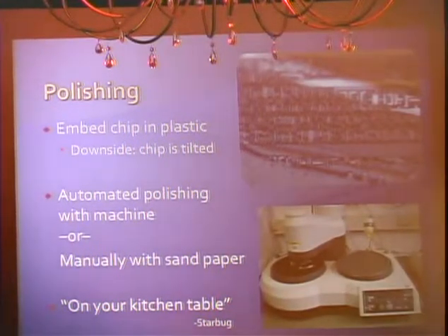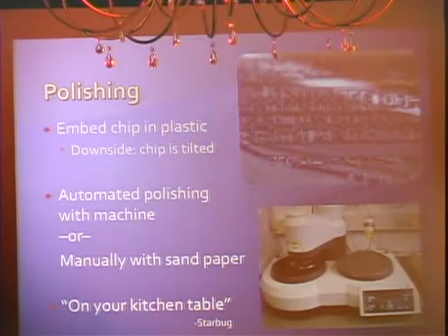One thing you've got to be cautious with, though, is that you don't want the chip to ever be tilted. And by tilting, I mean, imagine this chip to be some 3D structure, like a building. And now if it's tilted, you cut through different floors at the same time, diagonally. Okay? So you don't want that, because you want nice pictures of each layer. And you can imagine how if your chip is only a millimeter square, it's kind of hard to handle.